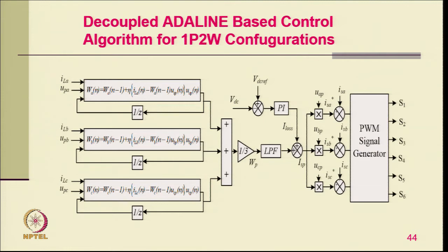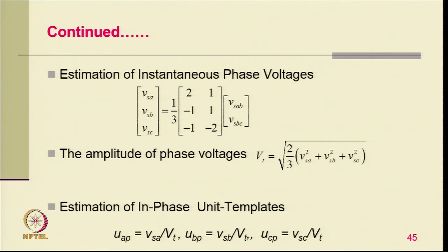Starting with the algorithm of the orthogonal line for single phase load, we take the load current and the template, which we discussed already in detail in the case of your D-STATCOM, for all 3 phases. Then we extract the fundamental active component of current from there. Then we take an averaging of it for load balancing, and pass it through a low pass filter. So, this gives us the active component of current for all the 3 phases. Then we regulate the DC link voltage for supporting the DC bus, and there we also consider the losses coming from the generator, and this gives the amplitude of the generator current. Multiplied by the template, we get the 3 phase generator current, which is at unity power factor. We sense the generator current and have a current control of this STATCOM, which is providing the compensation for the DG set.